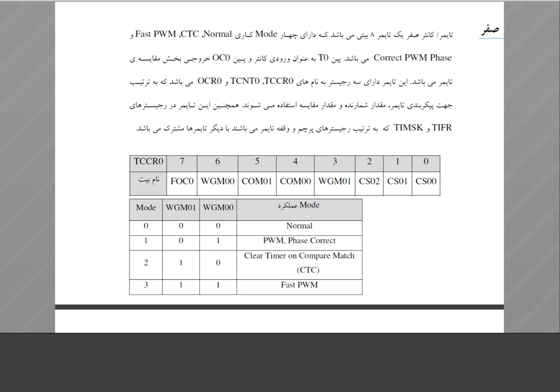For example, you are starting from 0 in timer 0, 1, 2, 3, and this is TCNT, the timer count. And this OCR may be initialized by you to 100. 0, 1, 2, 3, 4. When TCNT is 100 and OCR is 100, this is a compare match.